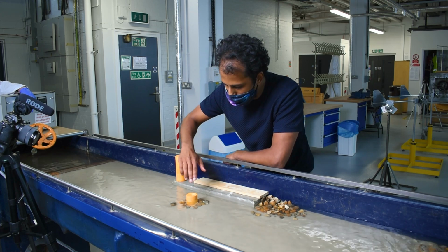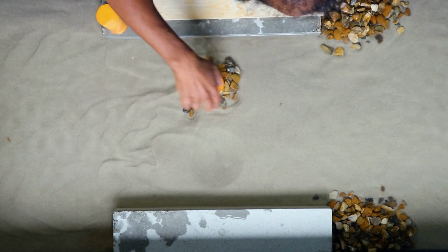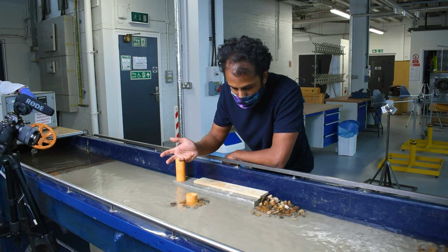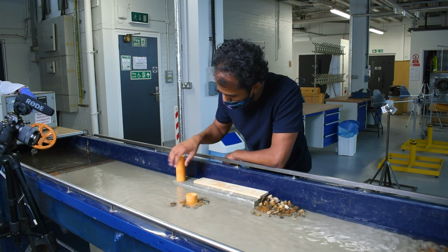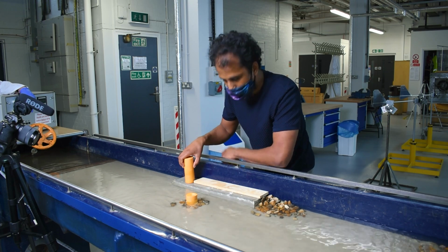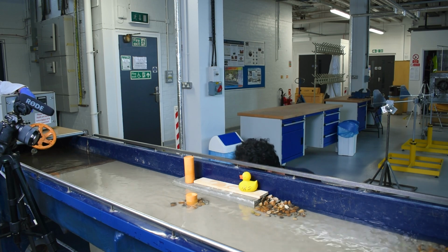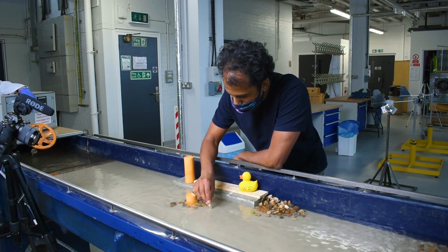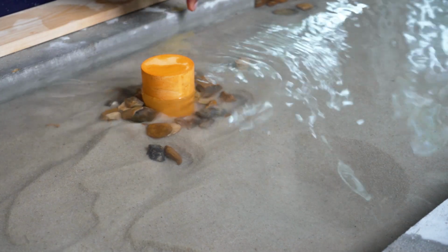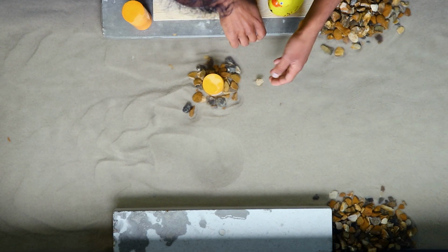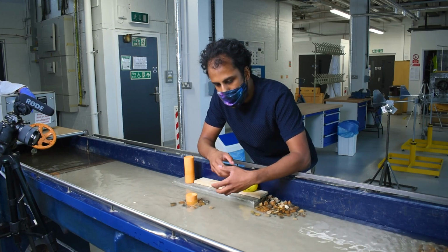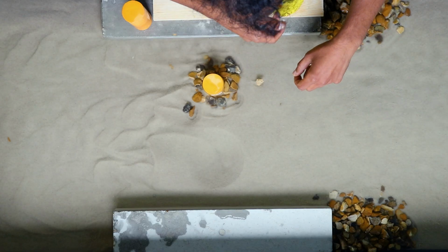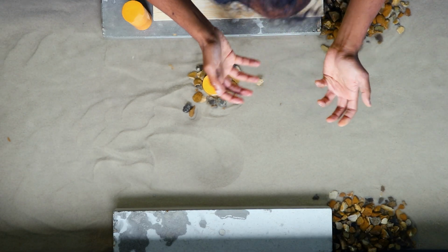Or you would have a steel collar which would wrap around the entire structure. Other ways of doing this is you could put another pier in front of it, like a little sacrificial pier. Here's one I made earlier. So you could pop that in. And the point of that is that when the flow approaches, this pier sacrifices itself to that flow, as it were, by allowing scour to develop around it.